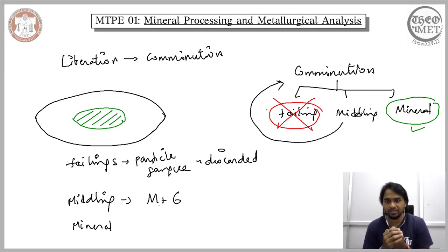So we go for two-stage comminution instead of a one-stage comminution, wherein at the end of it we get smaller particles. Even though the amount of mineral that is liberated is going to be the same, the two-stage process is economically more optimal when compared to the one-stage process, and it also helps us govern the overall flow of the process chain. What we mean by that is, we saw in the previous lecture, when we considered the practical aspects of comminution or liberation, there needs to be a balance between a few things. The first aspect is the amount of mineral that is being liberated.